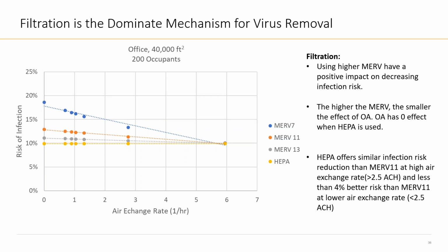research, and the ASHRAE recommendation and NAFA recommendation is whoever is changing the filter should use personal protective equipment, gloves, and put the filters in a sealed bag. This is really important for reps and service industries to educate and put signs and educate the industry about how to dispose of these filters. Really important.